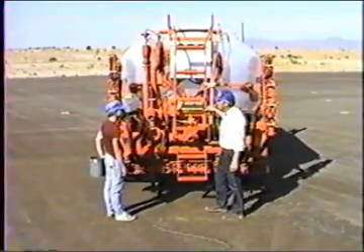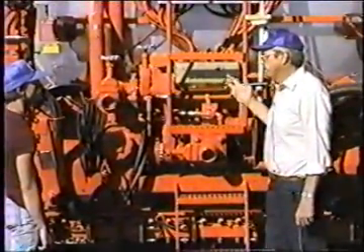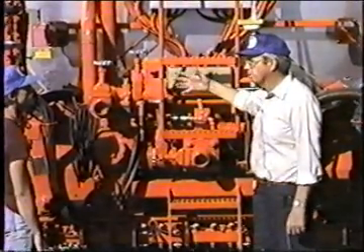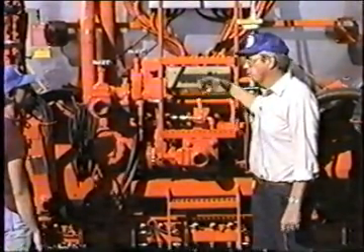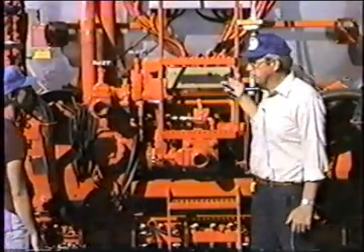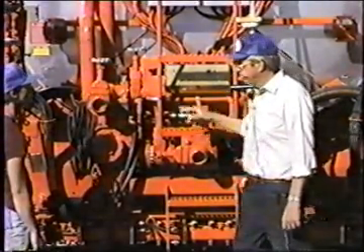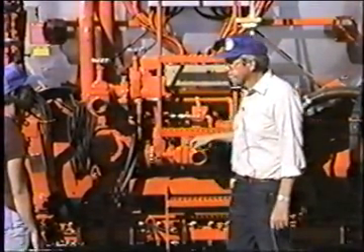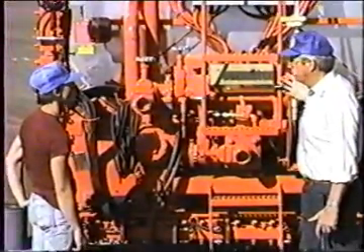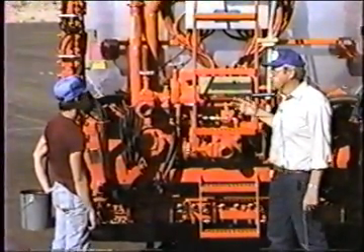As we drive up and back into that tanker, we have been spreading. That is, the whole truck is in the circulate mode. It's circulating when we're going down the road. Anytime we're not spraying and we're on the job, it is circulating. As we back up to the tanker, we're going to set the brake. As we get out of the cab of the truck, put the pump into full speed reverse. It was running forward. Anything else, the spraying, the circulating we're going to do, was always in forward. As we get out, put it into full speed reverse.